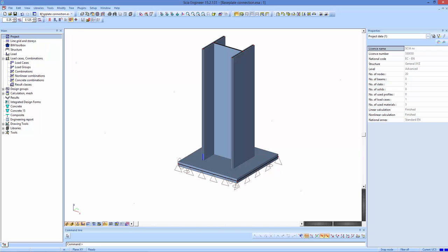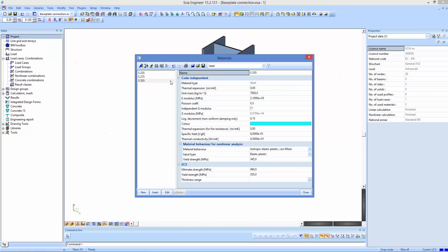About these material properties, I'll show you the used ones. I inserted a bit more security or safety in this project. So as you can see, for material S275 I inserted a maximal yield strength for plastic behavior during the nonlinear analysis of 265. Same for material S355, with an additional safety of 10 megapascal, using a yield strength of 345 megapascal as a maximum value.